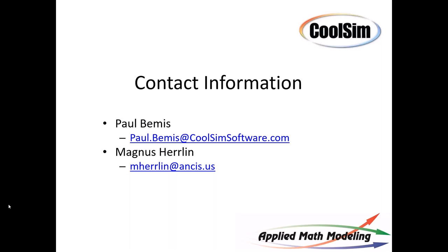What I see is evaporative cooling where you can get away with it, and also big free coolers, dry coolers, where you have large series of heat exchangers laid out there. I'd be interested in your take on this too, Magnus. Well, I think dry coolers are becoming more popular or feasible because we have higher temperatures in our data centers these days. Yeah, that's right, and you can get away with it.